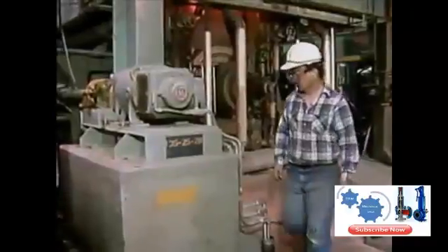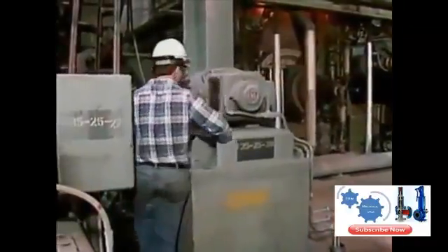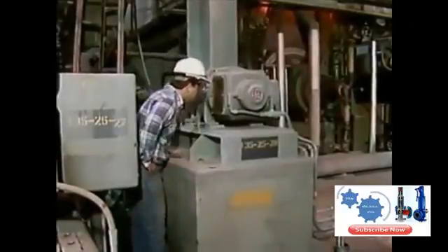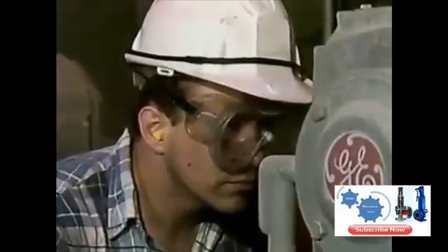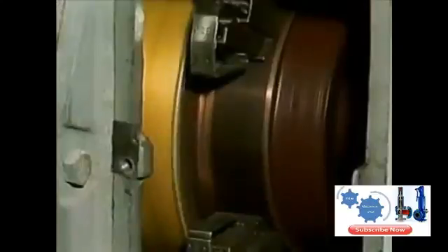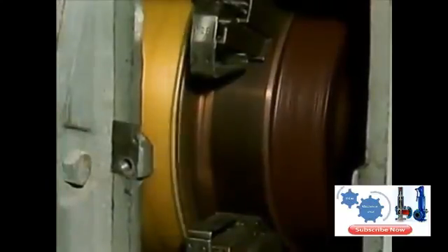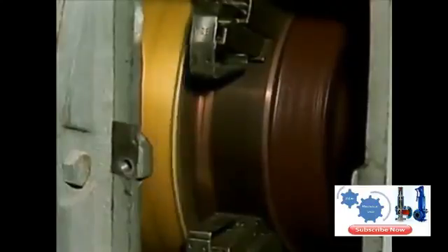Brushes are a frequent maintenance item for DC motors. Because they rub against the commutator, they wear down, so they must be replaced periodically. Sparking or arcing near the brushes or on the commutator can mean that the brushes need to be replaced, or that they're not making good contact with the commutator. In addition, brushes can chip, which impairs their effectiveness. The commutator should also be checked periodically. Any scoring or grooving on the face of the commutator may indicate a problem.